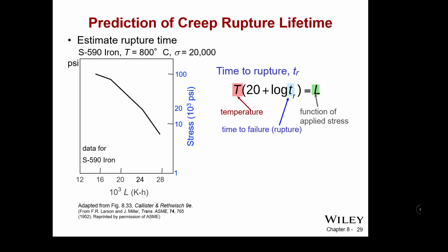So this is part of the reason why they would have to do work and replace parts on especially things like boilers, cast iron boilers and things. This is why these kinds of things happen. So these materials, we saw examples of boiler ruptures in some of the accident report things that we saw. Same kind of thing that's happening there. That prolonged high temperature use at a given stress over the course of time, especially with the thinning of material and all of these things.